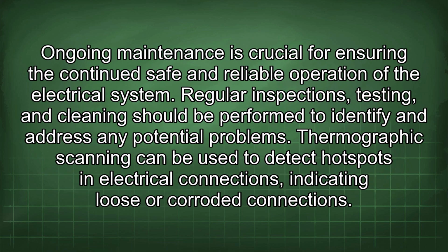Ongoing maintenance is crucial for ensuring the continued safe and reliable operation of the electrical system. Regular inspections, testing, and cleaning should be performed to identify and address any potential problems. Thermographic scanning can be used to detect hotspots in electrical connections, indicating loose or corroded connections.